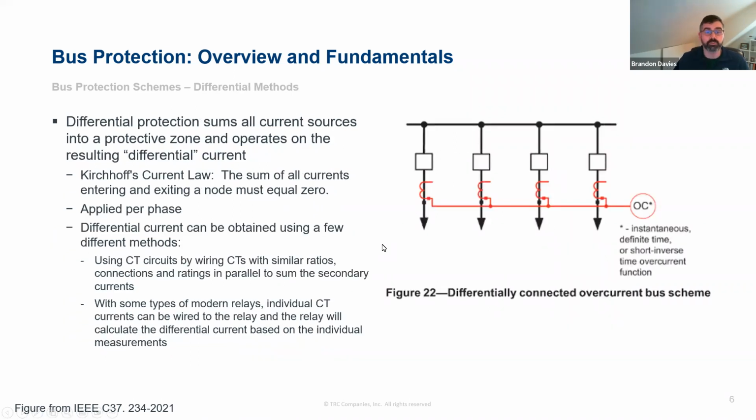Really what we see most commonly these days on bus protection is a differential scheme. We touched very briefly on differential protection when we were talking about pilot protections. You can protect a transmission line differentially as well. But we'll do a little bit deeper dive into that today on the bus protection topic.